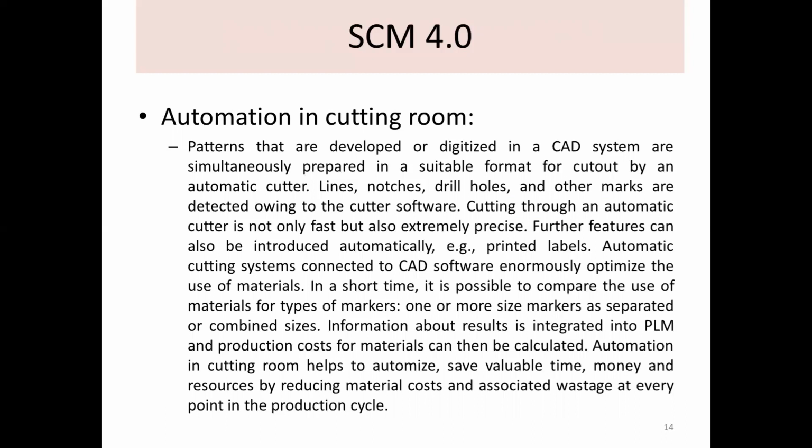After that, automation in the cutting room will be done. Patterns that are developed or digitalized in a CAD system are simultaneously prepared in a suitable format for cutting by an automatic cutter. Lines, notches, drill holes, and other marks are also done by the cutter software. So this automation can reduce the operating time, and accuracy can be increased.